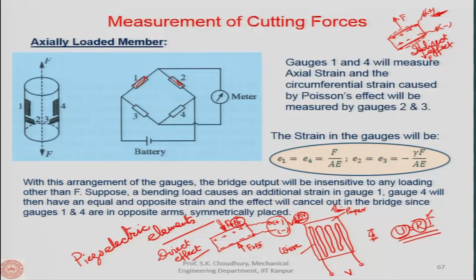Ultrasonic machining is with the help of a very high frequency vibration, and that high frequency cannot be produced with the help of an electromagnet. By high frequency, we mean about 20-25 kilohertz. So, 20-25 thousand times per second, it is the vibration.